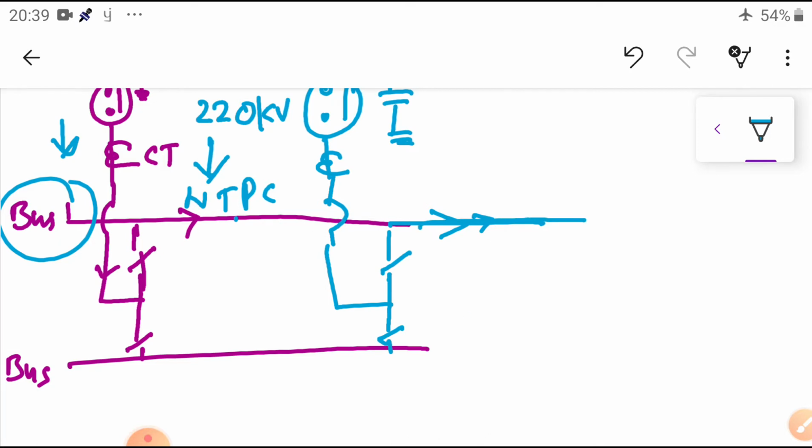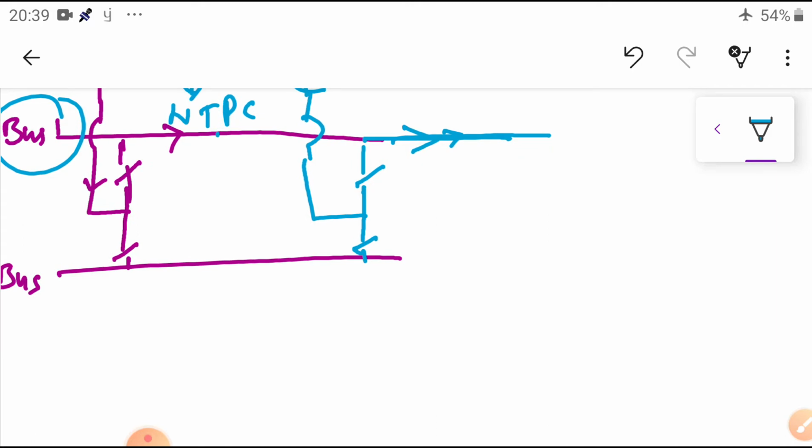Here, from the substation, I am going to connect my system, where I am going to have my transformer primary and transformer secondary. On the transformer primary side I am going to connect the lightning arresters, and before that I am going to use the isolator.